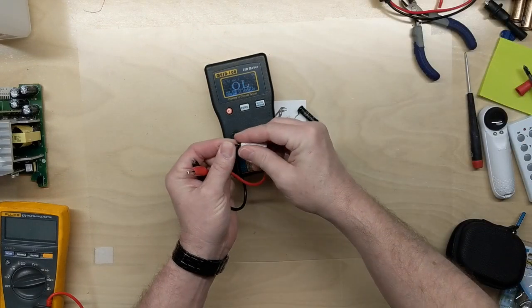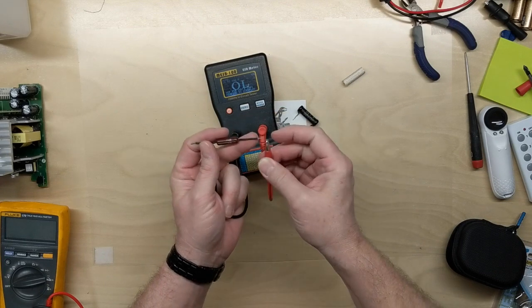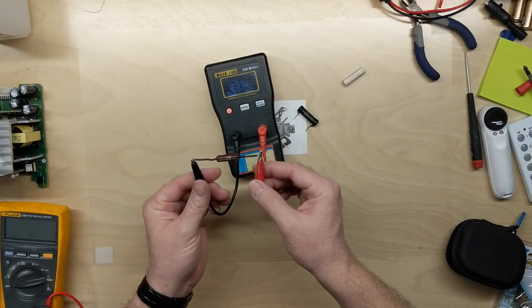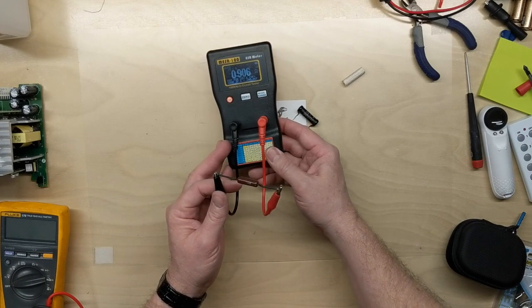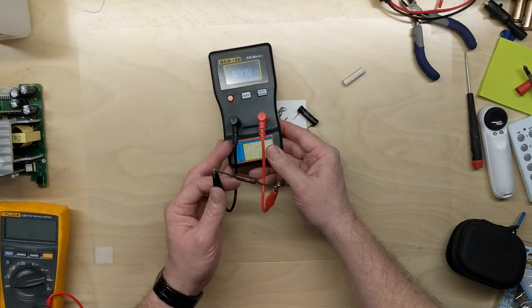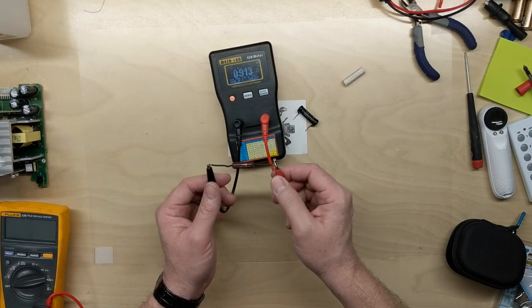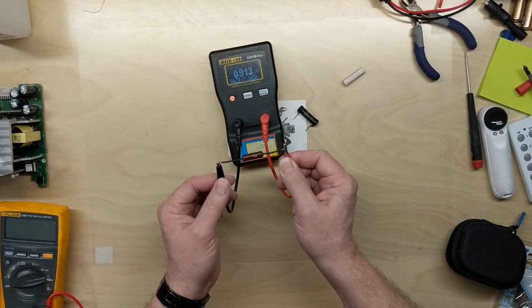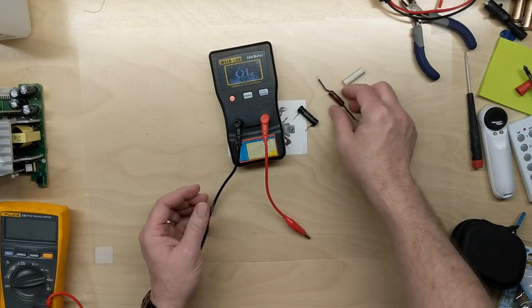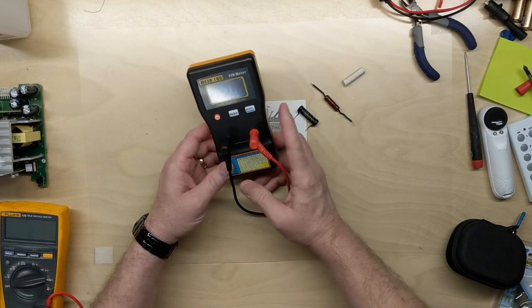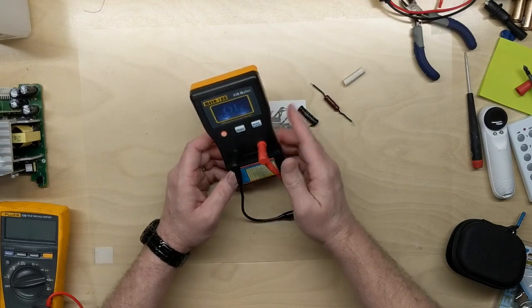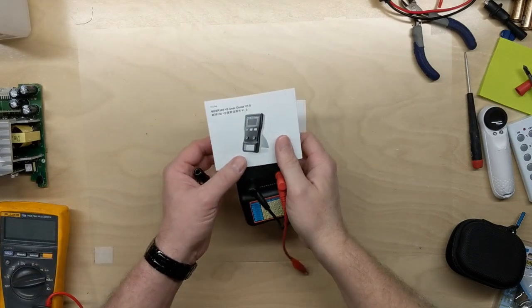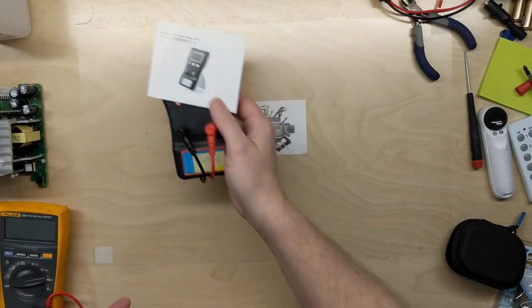So if we look at the actual resistor we're checking with, it's not a precision resistor, but we see that it is relatively close, just for testing and showing as an example today. It's right at 0.9, so 0.91. I just thought I'd share that. Of course, ESR meters typically are good for your lower ohm scale. So if you do have one available, it can help a lot with checking your low ohm resistance.